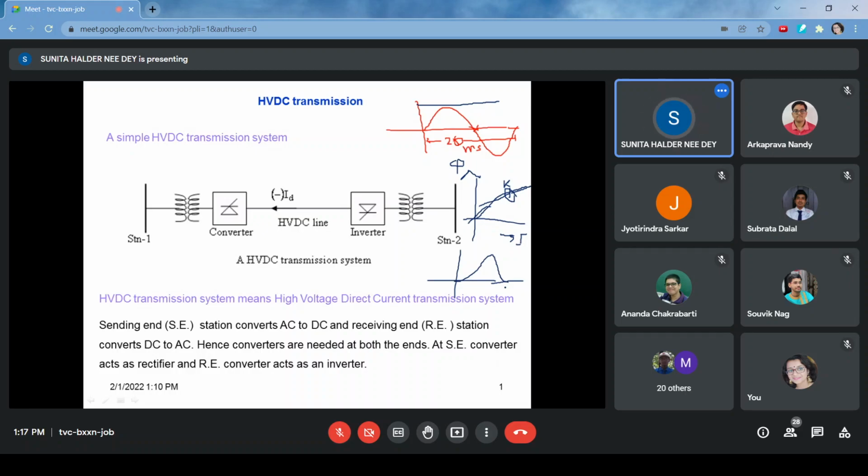So that is the thing. Anyway, harmonics are there. Harmonic sources are there in the normal AC system also, due to the saturation of the cores. Even in the machines, in the same way. But that is not so prone as in the switching devices. In switching devices, the presence of harmonics will be far higher than in the normal AC systems.